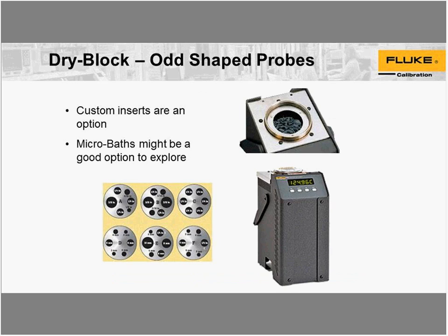Today, you may find yourself trying to use a dry well with some off-shape probes. We do sell blanks and custom drilled inserts that do work, but there are considerations with these probes if they are extremely short, or the mass of them is outside what we would expect.